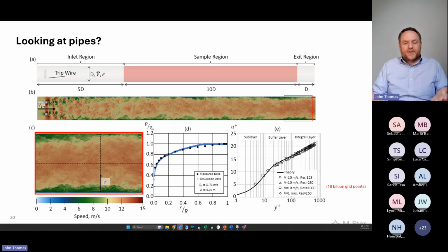That the turbulent spectra shouldn't care how it got there, right? If we have a free turbulent flow, yes. If it's narrowly wall bounded, there might be issues. But if we have a sufficiently large diameter that the length scales of the turbulence are small compared to the integral scale, where there's an agitator, whether it's a pipe flow downstream of a turbulence trip, foundationally we're going to have the same general Kolmogorov spectra, the same energy spectra, as you get down to the integral and Kolmogorov length scales. And so these physics should work.